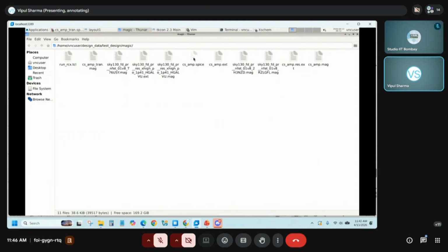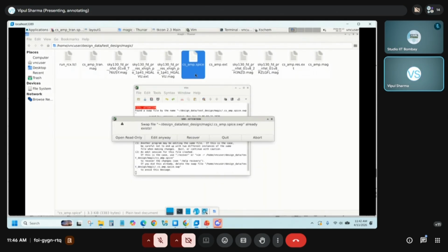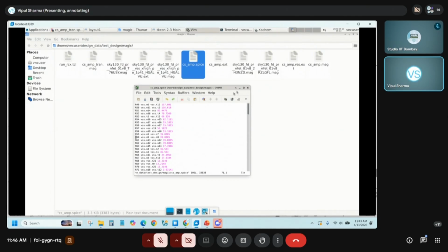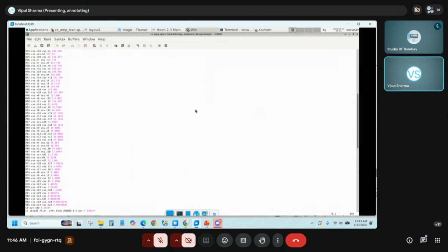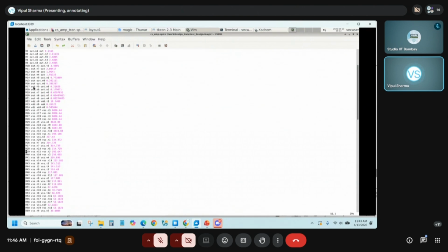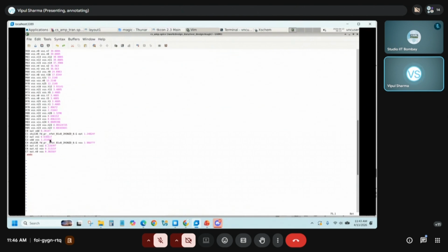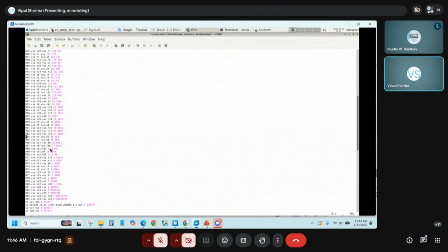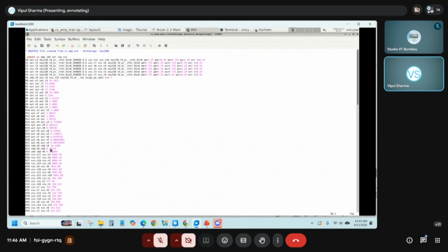Okay. So let us see this file. Yeah. So this is how a parasitic netlist file will look like. Let me show you. Yeah. So these are our fingers, 5 fingers of our NMOS, and this is our poly resistor. But besides it, we see these number of resistors and also capacitors which have been extracted from our layout. So this is something additional, and this was not part of our earlier ideal schematic, which we use for